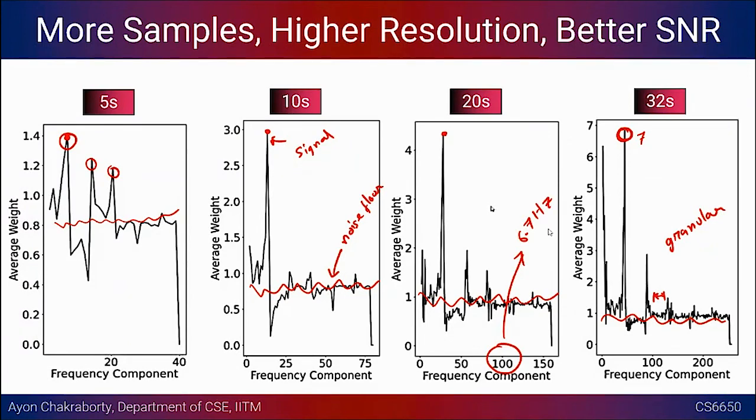Yes, sir. Right, I'll give you a short answer for today. It basically depends on the sample rate, because if you are doing 16 samples per second, let's say, what will be the maximum value of your frequency that you can track? 8 hertz. Yes, sir. Okay, so that is uniformly scaled across the components. So I think you can take this one as, let's say, 0, and this is some kind of an F max. If you know 0 and F max, you can do a simple unitary method to find out what this means.